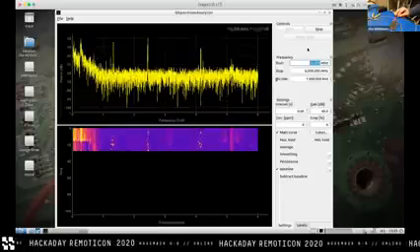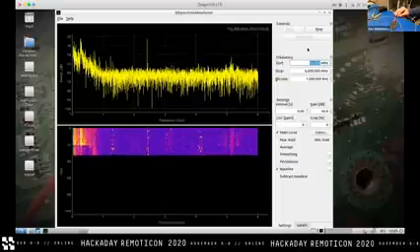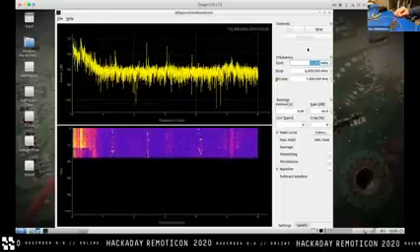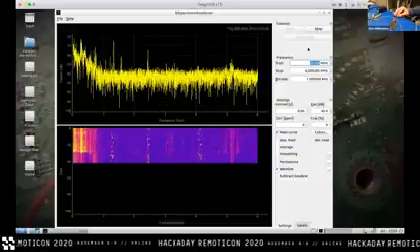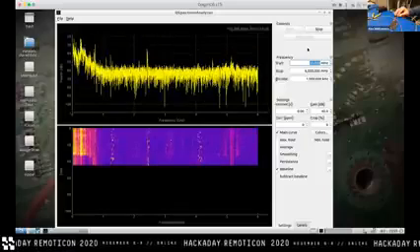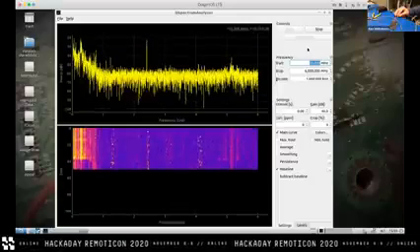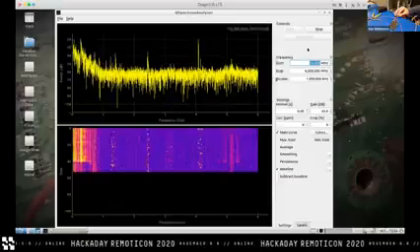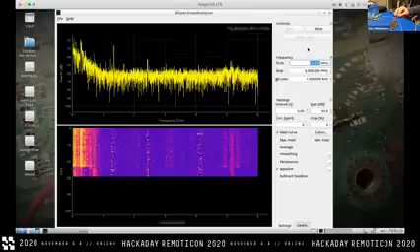I am nearly certain those aren't our device, especially given how intermittent they are. But keep in mind that I am immediately next to a mesh network base station blasting 2.4 gigahertz frequently enough to mess up all my Bluetooth devices, and also 5 gigahertz Wi-Fi. So I'd be willing to bet that 2.4 gigahertz spike that keeps popping in is that router.